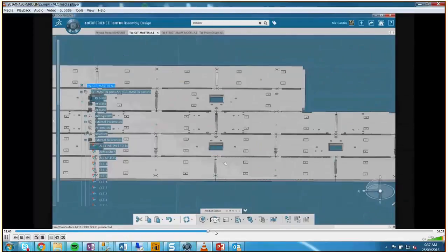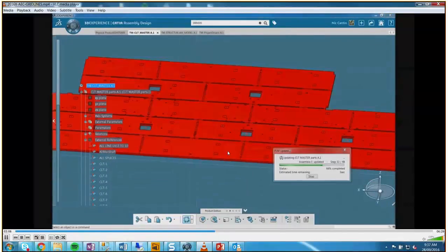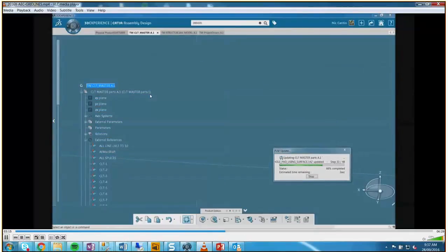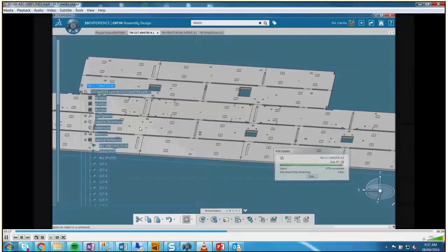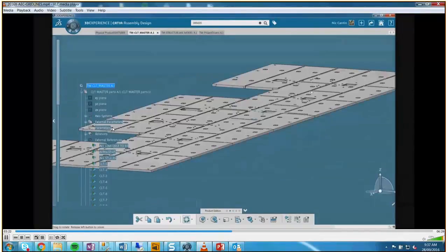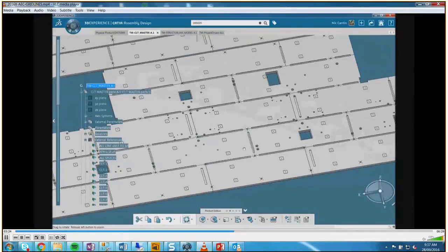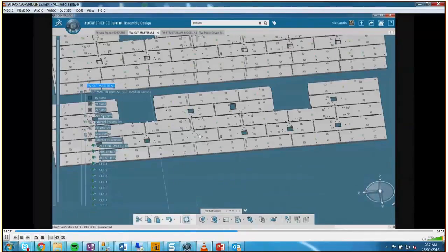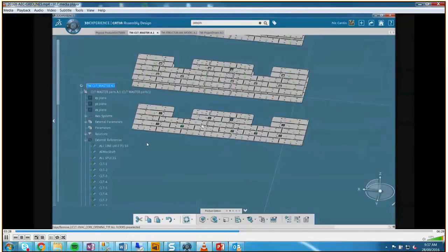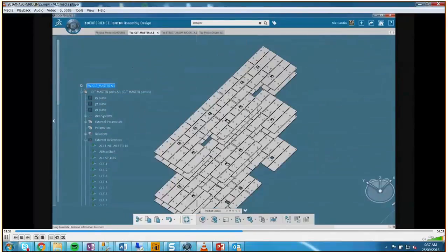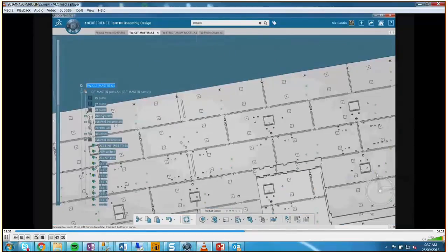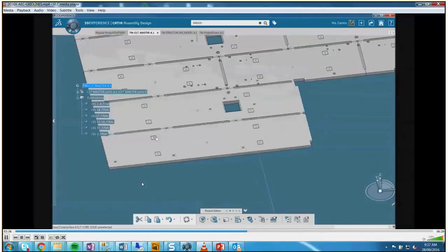So now we've made a few modifications to the drivers. We've shifted a grid line, moved one of the penetrations for the HVAC mechanical assembly, and now we're just updating the master level. Essentially each panel has the same outline, same profile. So we were able to update level 3, and levels 9, 10, and 18 would update as well, just for the profile.